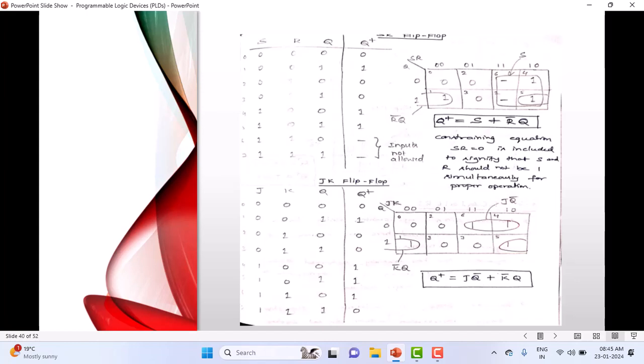Okay, last one, you can see it is the forbidden state in case of SR flip-flop. The last state is input S equal to 1, R equal to 1. Present state is 0. Same way, input 1, 1, present state is 1. I have taken two combinations of present state. What is present state? It is what you are assuming, right? Before you switch on the SR flip-flop, give power to it, input data, present state, at output you are observing this. This is going to be the present state 0. When the input you applied is 1 and 1, the next state is going to be the undefined state. What is undefined state? Both going to 1. That's called undefined state. We don't expect this. This is called forbidden state.